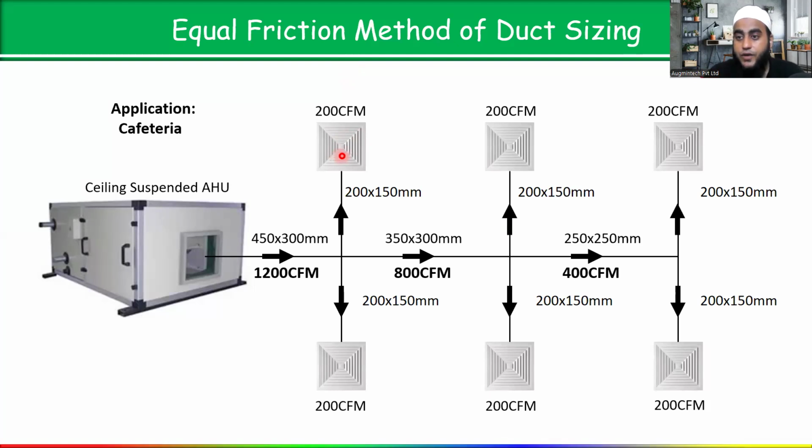In areas where noise is a concern, like when you are designing a hospital building, where we have to reduce the noise level, it is better to go for a plenum. Use the diffuser with a plenum box. For that we have a complete design method.